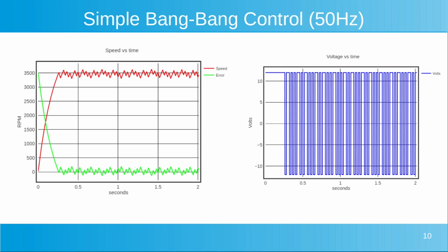An important thing to note with bang-bang controllers is that you need to use the full range of the motor in order to be able to use the full range of the output. The response variable has to be the maximum possible that your system can provide. Otherwise, you can't use the full range of it, which is fine for a set point like this, which is in the middle of the range, but if you try to change the set point, you're going to have problems.